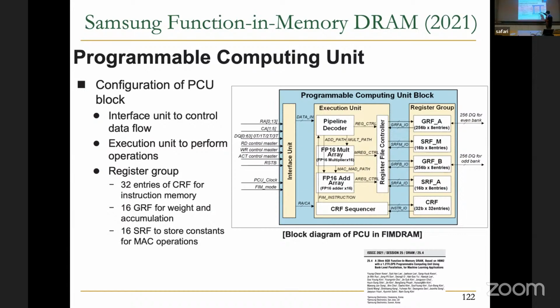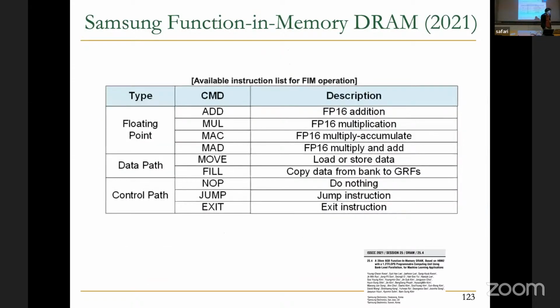And this is sort of the pipeline, starting from the decoder, multiplier, adder, and then controller to access the register file, either to read instructions or to read and write operands or data. And this is the reduced instruction set, because you need what you need, right? That's why it's important to understand the data and understand the applications and the algorithms as well.